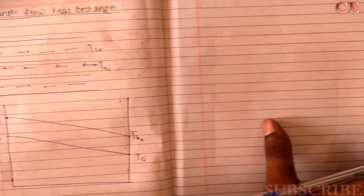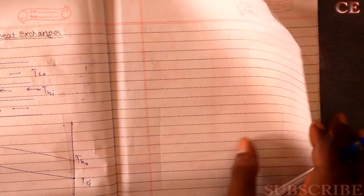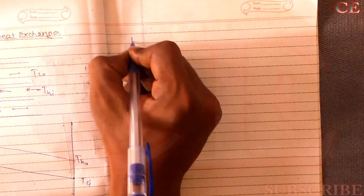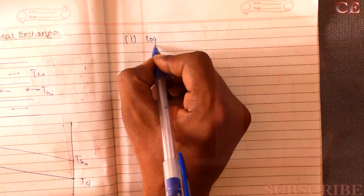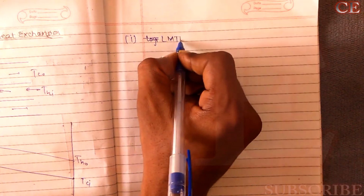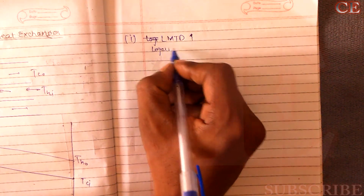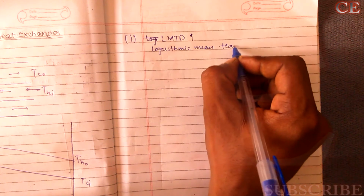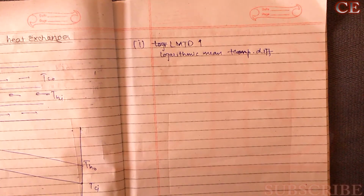Now we'll understand how counterflow heat exchangers are better than parallel flow heat exchangers. There are several reasons why it is better. The first one is that it has a larger value of LMTD. LMTD is the logarithmic mean temperature difference. The advantage of having a larger value of LMTD is that it permits a small heat exchanger area